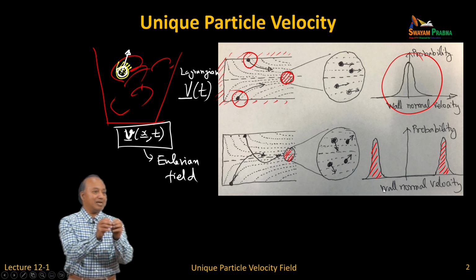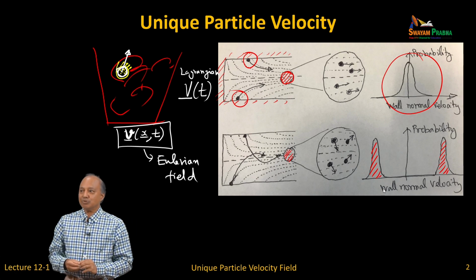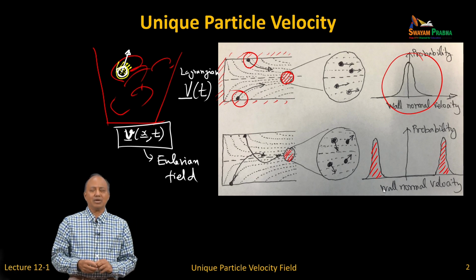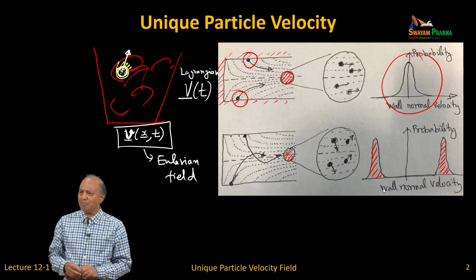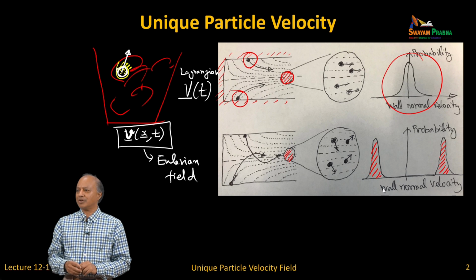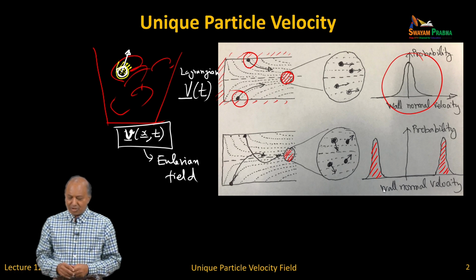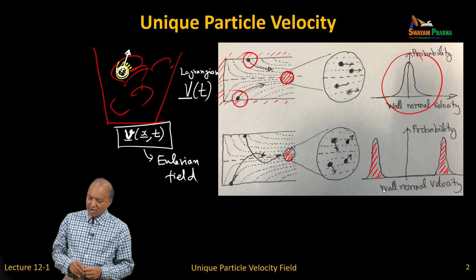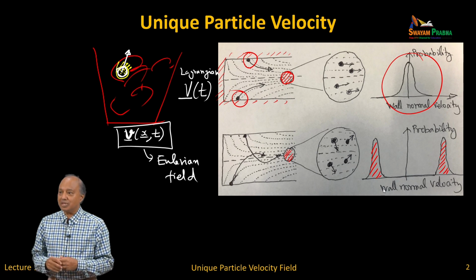It's not because particles were interacting. So when I say Stokes number must be less than 1, the question that I am asking is, do these particles have long memory or do they forget? Okay. It turns out the answer is, if Stokes number is less than 1, particles forget, and therefore the Euler method is in good shape.